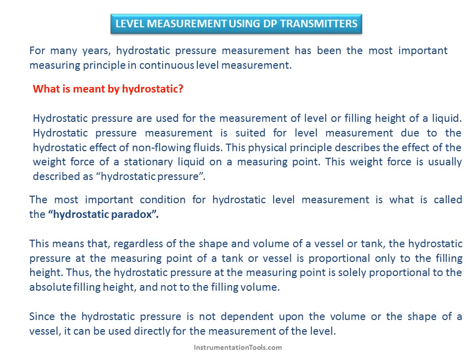For many years, hydrostatic pressure measurement has been the most important measuring principle in continuous level measurement. What is meant by hydrostatic? The effect of the weight force of a stationary liquid on a measuring point. This weight force is usually described as hydrostatic pressure.